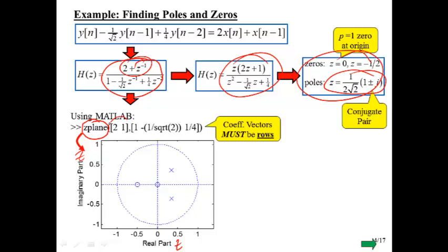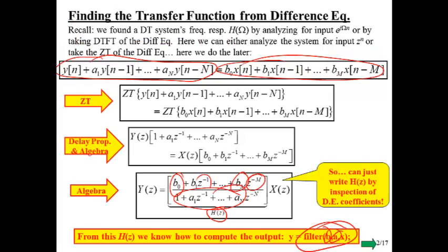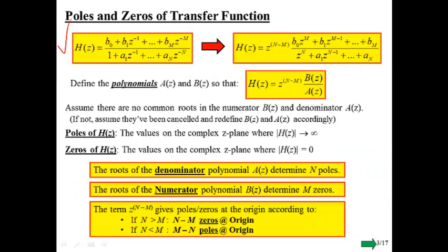So we just populate the coefficients, numerator and denominator. So it's a good idea to keep track of these commands and what order you put the numerator and denominator in. I think it's pretty consistent. If we look at this filter command, it's numerator and denominator. Same thing with the zplane.